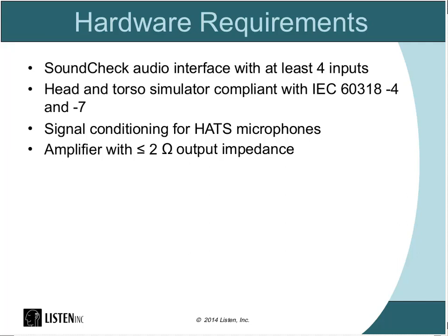Depending on whether they're 200-volt polarization, you could use our Listen SoundConnect to power them. If they're pre-polarized, you could use our Listen AmpConnect to power them, or any other signal conditioning that you have. And then if you're going to run the -2 analog headphone test, you'll also need, like I said before, an amplifier with less than or equal to 2 ohm output impedance. So that would, again, only be if you're running the headphone portion of the -2 standard.